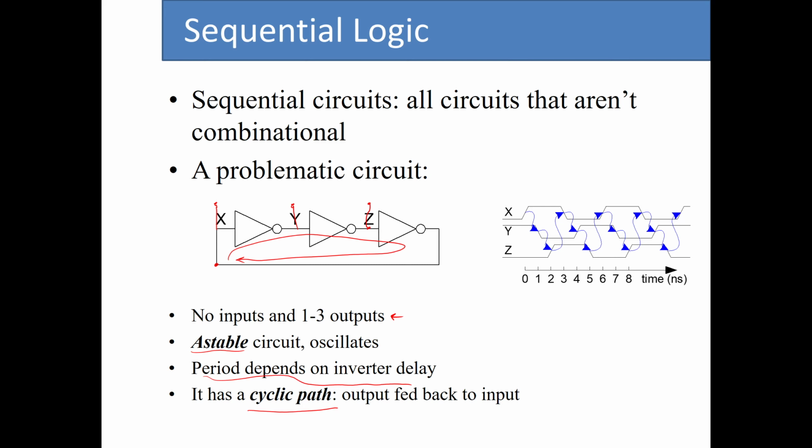this type of circuit. And the same way that we started with the state element, we started with the bistable circuit, and we realized that that is not good enough, and then we moved forward with the further design. We went from the bistable circuit to the SR latch, to the D latch, and finally we ended up at the design of the D flip-flop.